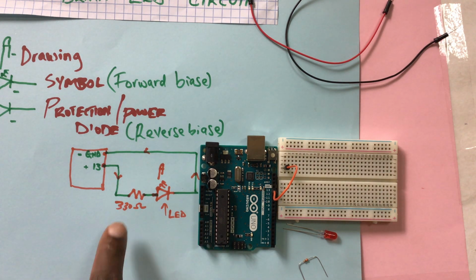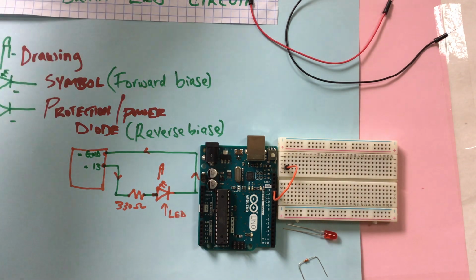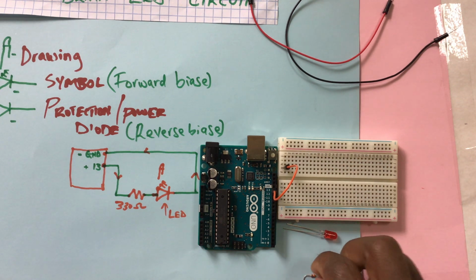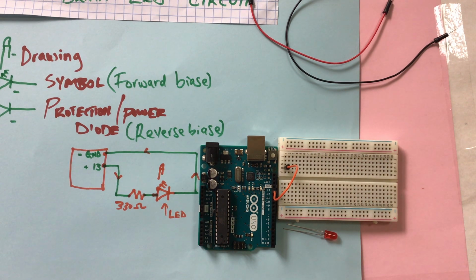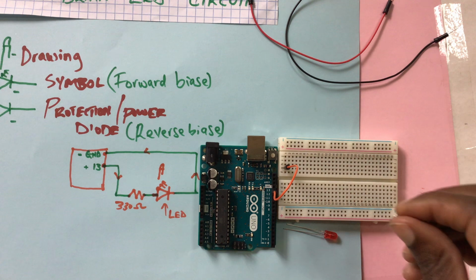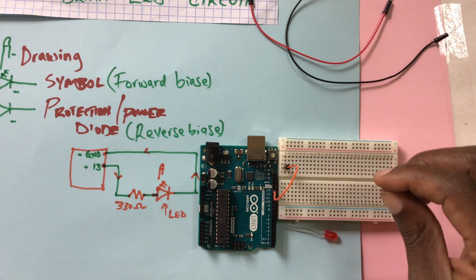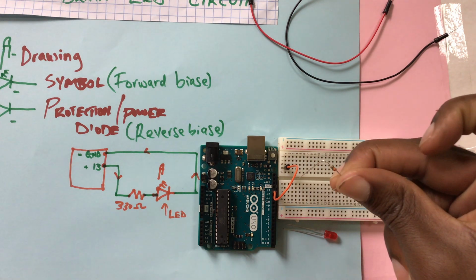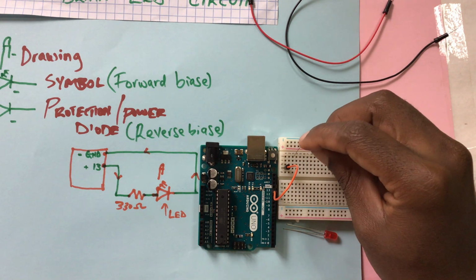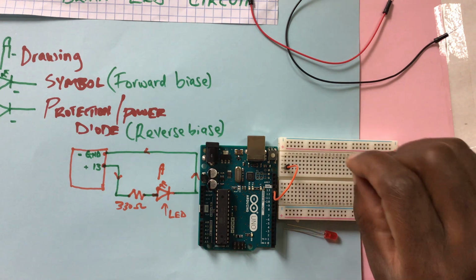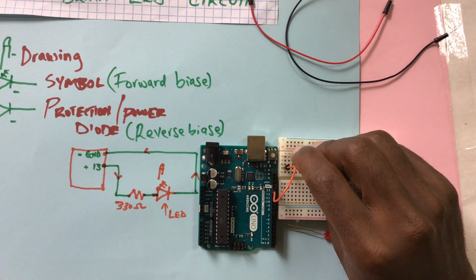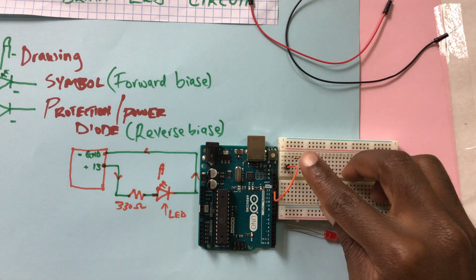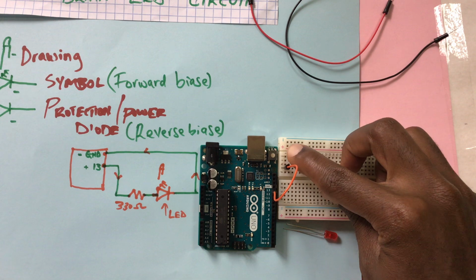So after that, where are we going next? We are going to our resistor. So our resistor, we're just picking in the same line, this line which has number 1, this vertical line having number 1. So it will be connected internally. This is a 330 ohms resistor. So we're going to use number 1 and 7. It's connected to number 1 and 7.